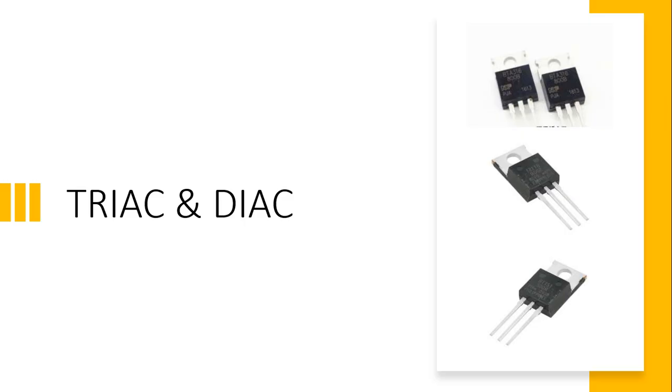So TRIAC is an anti-parallel connection of two SCRs. Since SCR is a unidirectional device, if we connect two SCRs in anti-parallel, the construction is the same as that of a TRIAC. And DIAC is an anti-parallel connection of two diodes. Since a diode is also a unidirectional device that can carry current in one direction, but the DIAC is capable of carrying current in both the directions. So both are bidirectional current carrying devices.